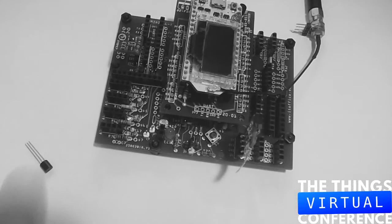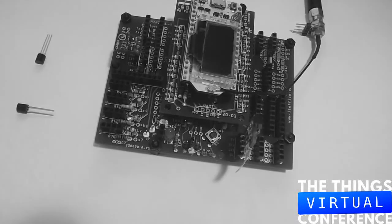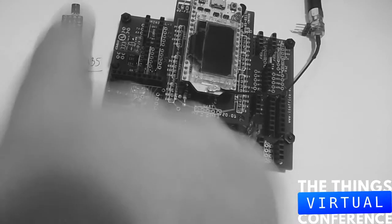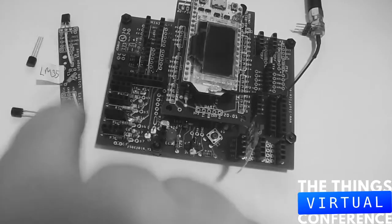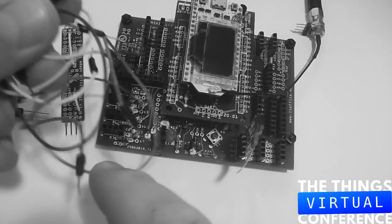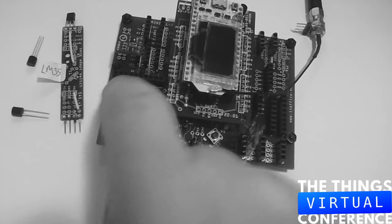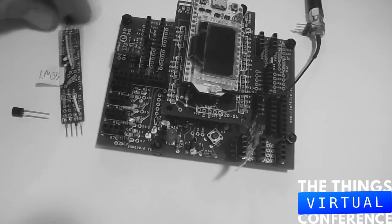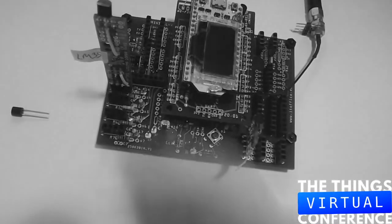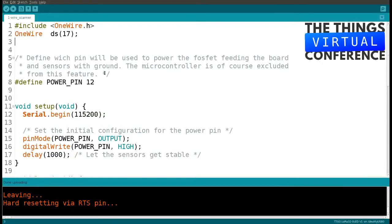Okay, and that was this one. Then we have the LM35, and it happens I have put an LM35 on this PCB, and there's nothing here. It's just wiring. This is just replacing this. So I have here a fixed connector, and I have some spaces here. The sensor is the same. And I'll put that in here on this channel. So here I have 4 channels for analog sensors. And we are in this program.